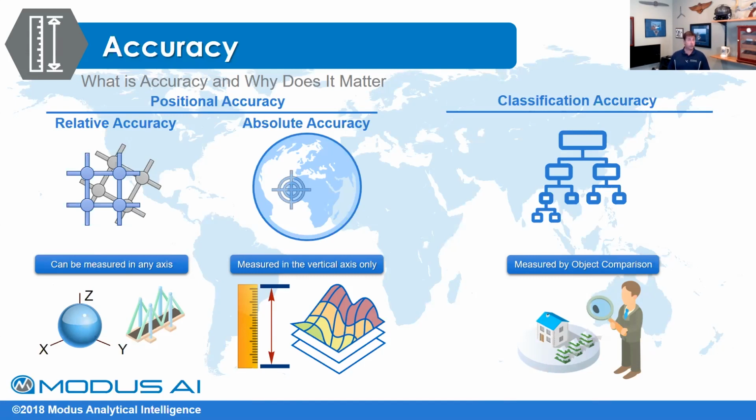For the folks that are dealing with photogrammetry, as a good example, your first initial product when you take it out of processing is a relative point cloud. And it's not until you actually sync with your ground control points that you're able to snap it into a coordinate system and then test the individual points to see if it matches your benchmarks.